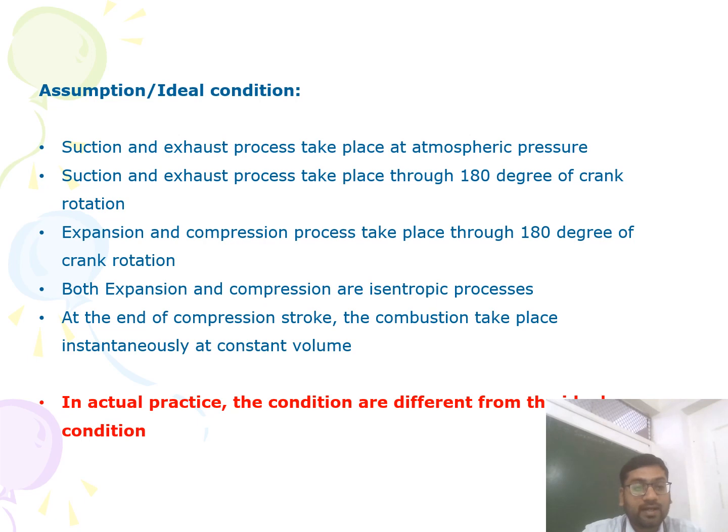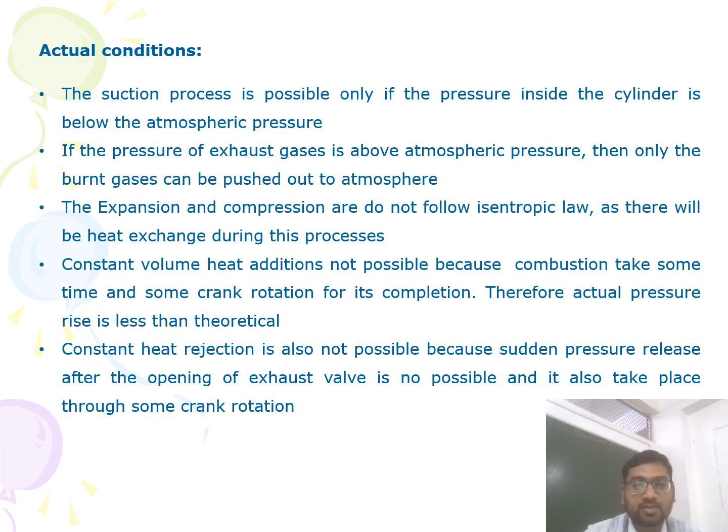Last assumption: at the end of the compression stroke, the combustion process takes place instantaneously at constant volume, meaning without any time consumption the combustion is completed. But when you look at actual practice in the actual PV diagram, the condition is totally different from this theoretical or ideal condition. So in the next lecture, next PPT, we will learn about the actual scenario in actual working conditions.